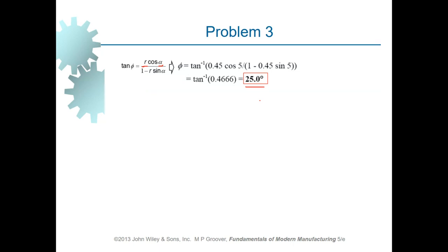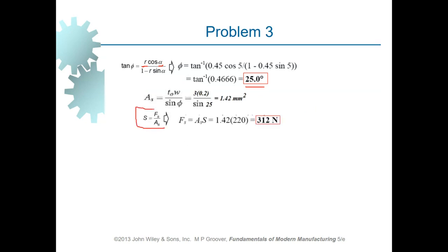And the next thing that we need to compute is the shear force, Fs. How do we compute shear force? In order to compute shear force, we make use of this equation here, and as I mentioned before, Fs is included in this. S is given, the area of the shear plane is not. So first we compute the area of the shear plane. Width of cut is given, which is indeed equal to feed. In turning operations, the width of cut is represented by w. But in turning, w can be substituted by feed, and the value of feed is also given, that is 0.2. Well, t0 is given, and also phi is just computed. So we can easily compute the area of shear, and when we have the area of shear computed and S, which is shear strength, and that is given, we compute the value of shear force.